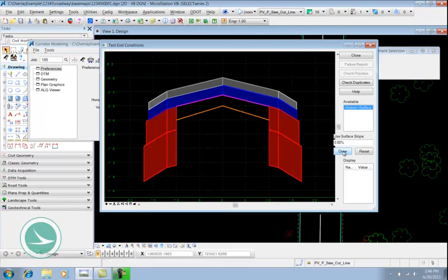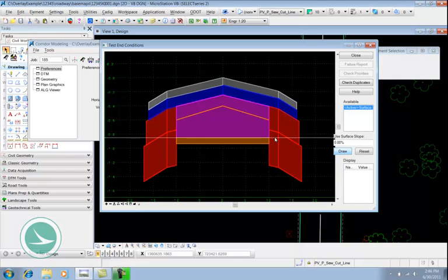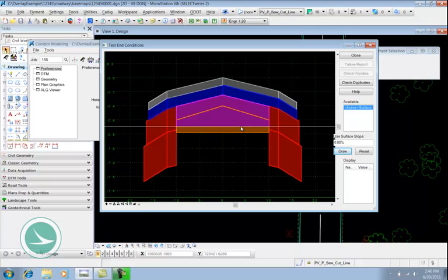So I use the draw button to simulate existing ground, and as I move over you can see the white line represents the location of existing ground, or the top of my pavement. And you can see in purple my wedge course, the top of it follows the component that it was constrained to, and the bottom of it meets my existing ground.